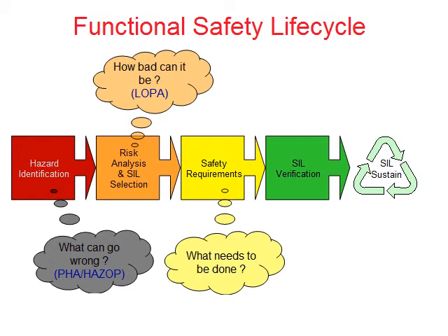So you want to be pretty specific in the safety requirements spec, as far as even concentrations, specific areas where it's of a concern, and obviously the gas that you're looking for.